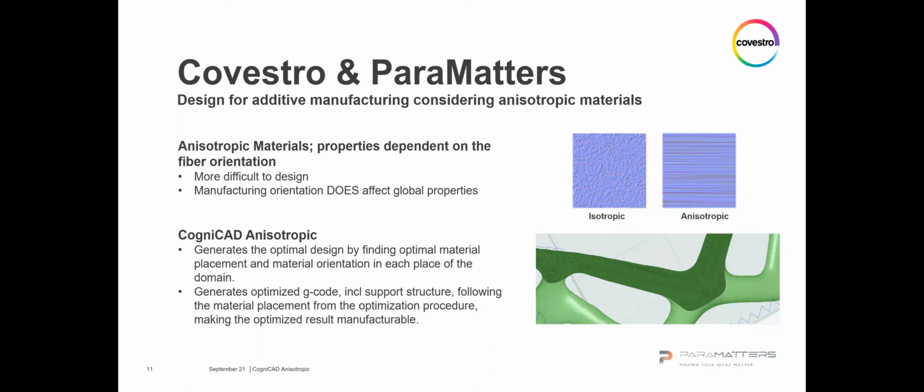First of all, what's the difference between isotropic materials and anisotropic materials? Isotropic materials are materials which have similar material properties in various orientations. For instance, take metal and try to make tests, pulling it in direction X, Y, and Z. We will see that material properties in all these orientations are more or less the same.